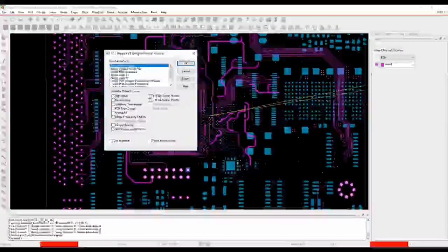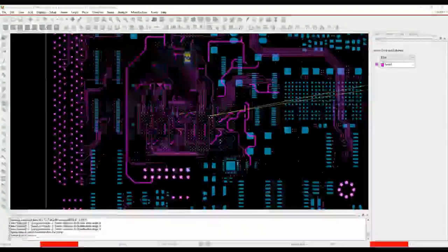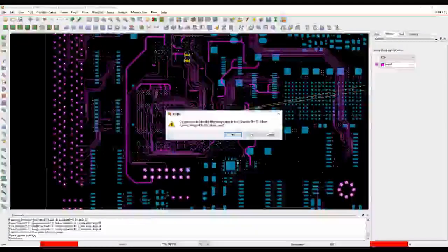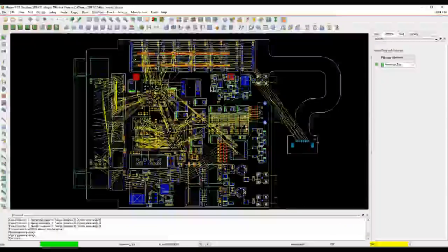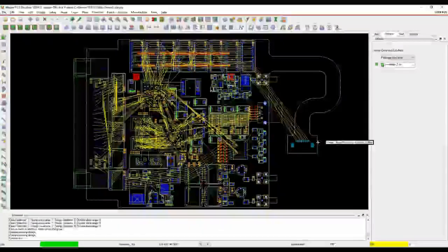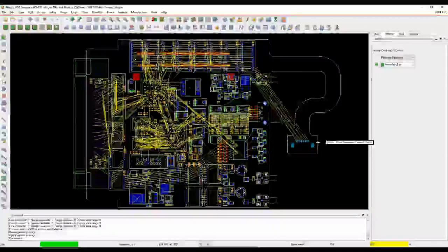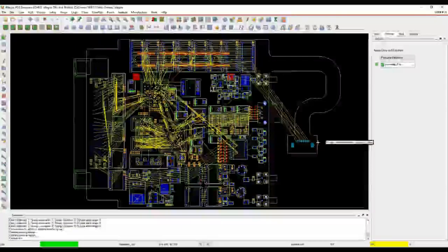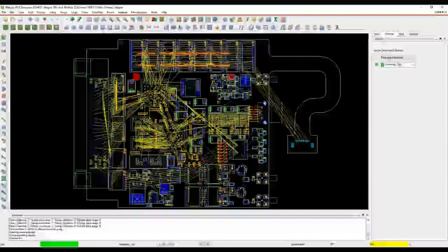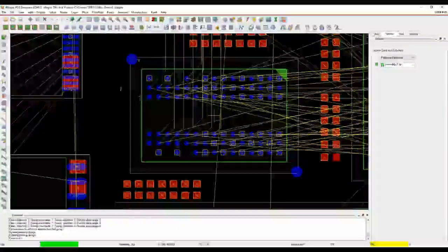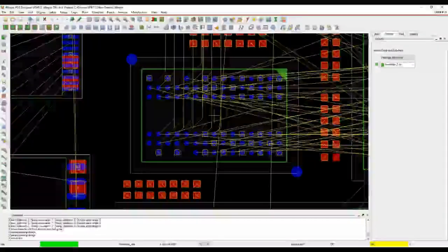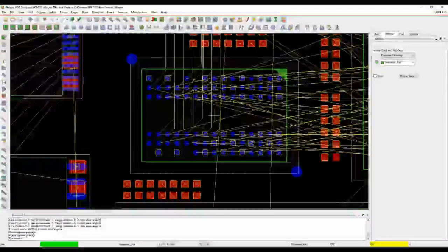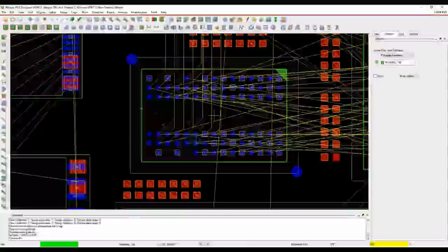Okay, so what we'll do now is drop the high-speed license, and we'll open another design, and we'll open something called the DFA. So with Allegro PCB Designer, this allows you to set up a rule set when you're placing components. In general, in an OrCAD-based license, you have something called a place bounds, top or bottom, and when you move these components around, you can have the placement boundary touching.